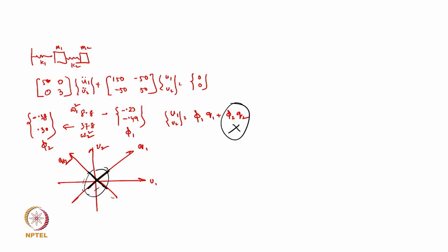So we just forget the remaining 95 modes and take only the first 5 modes. That is a similar case. Obviously I cannot write 100 equations and draw that. So I'm just thinking, if we have a 2-degree of freedom system, and instead of taking the 2 modes, I take only a single mode, what exactly are we solving?